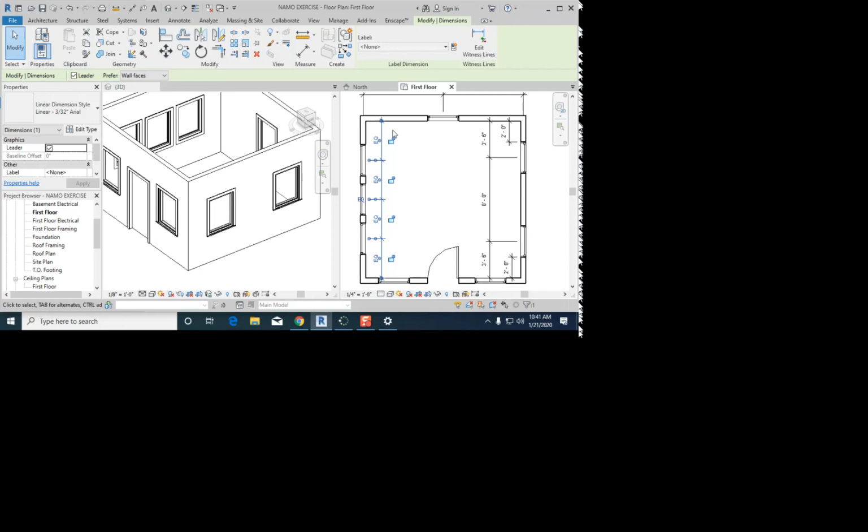Now remember you have to click on what you want to move. So what do you want to move? Now see how your dimension is highlighted? Not that one, that's not the one we're using. Get that one. And what's my new dimension? 2, enter. Go ahead and do the move constraint, because since you've made them equal, it's like, wait, do I move this or not? Now go ahead and hit escape for me.